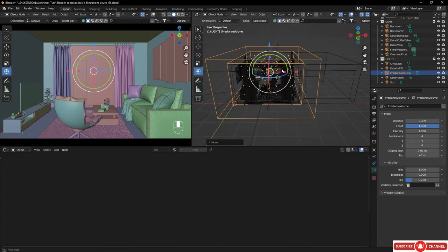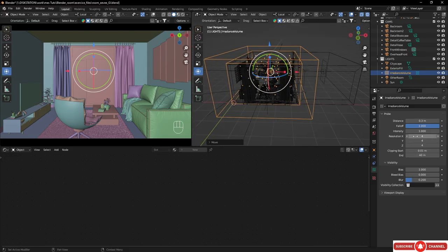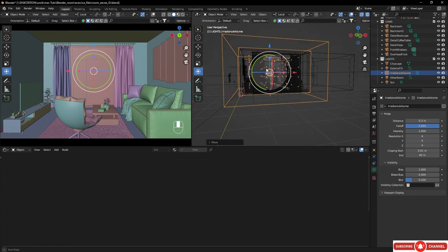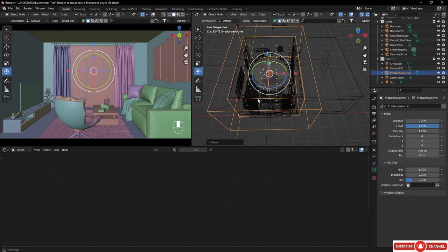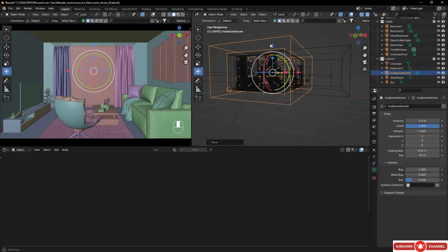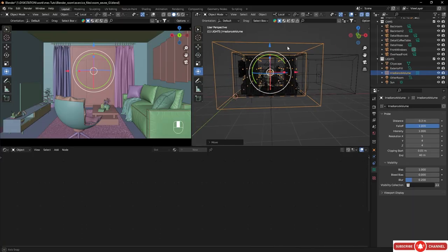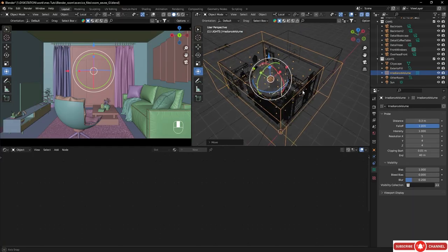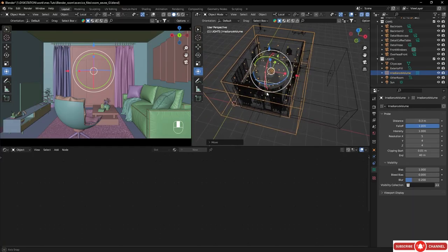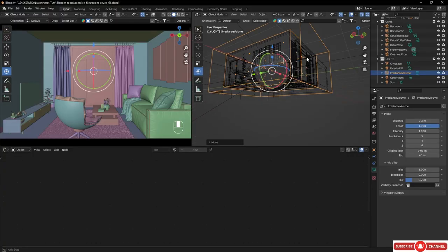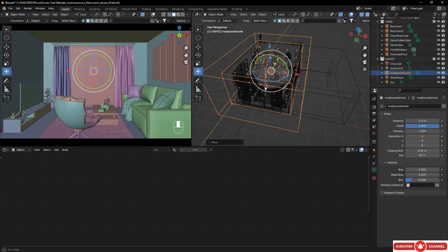We're going to keep it this way. The basic resolution here, 4 by 4 by 4, is important. It means how many spheres we have. So what we can do maybe is change just the x-axis to add a bit more samples this way. Okay, it doesn't need to be too thick, too dense, because it's going to lead to other problems. For this scene, which is very well lit, it should be enough.